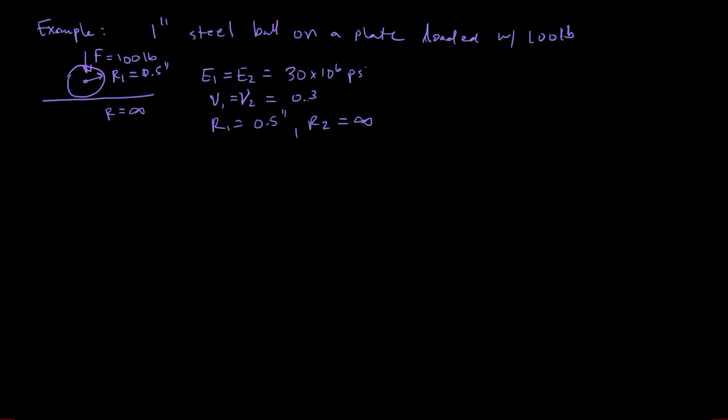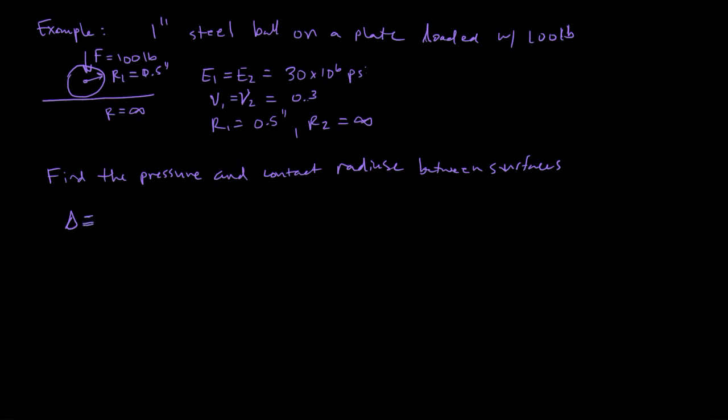So the question is, find the pressure and contact radius between the surfaces. Okay, and so we can go into our theory and find our contact modulus. In this case we use the contact modulus between spheres, and we treat this as a sphere with an infinite radius.